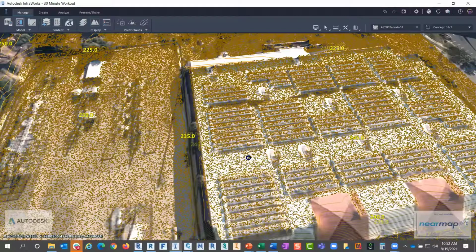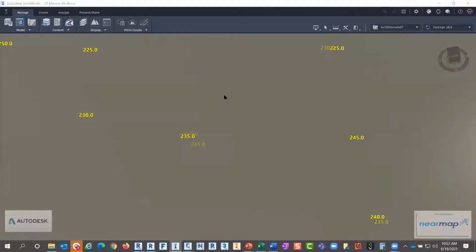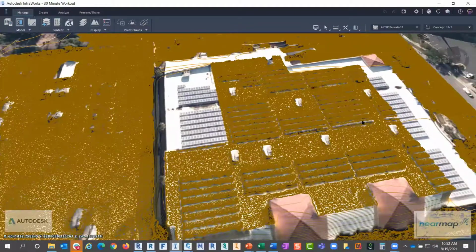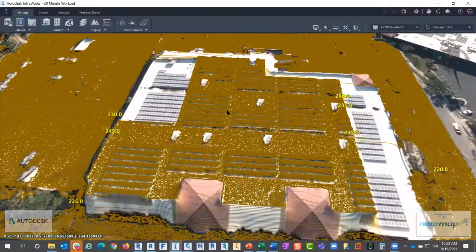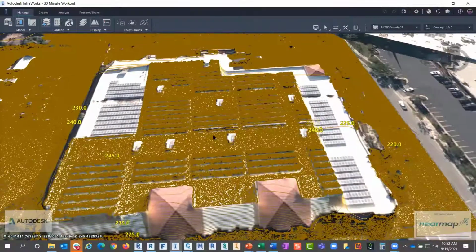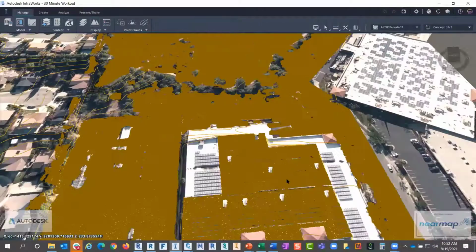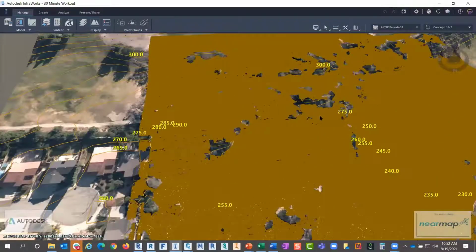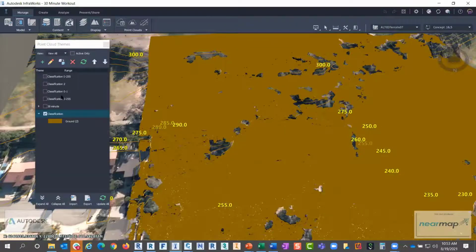What it did was, even with the bigger processing window, it was able to determine portions of the building top that were not ground. You can see those portions now are not highlighted. But that building top is still so large that it still found a bunch of points and said, well, they must be ground, because I still see them. In much of the model, it was able to determine things perfectly. Let's do the point cloud theming again. Let's classify, remove that, and classify everything.